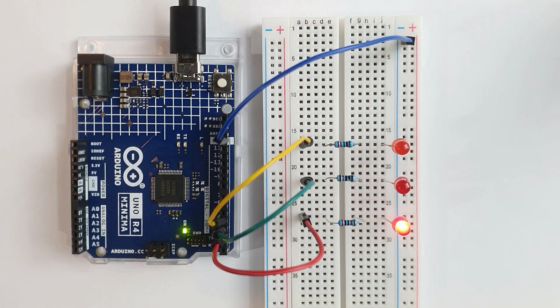For your challenge activity, choose 3 GPIOs on your Arduino UNO board and connect the 3 LEDs using different resistors per LED. This should produce different brightness levels. To practice your previous programming skills, write a program that turns on these LEDs one after the other and then loops repeatedly.